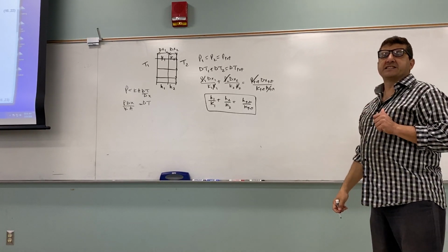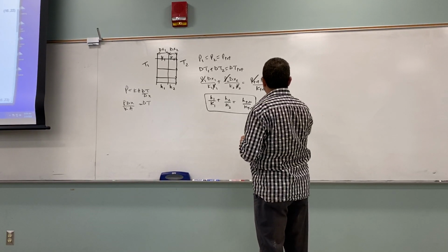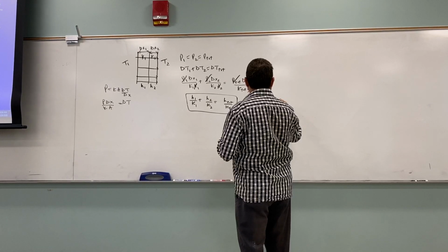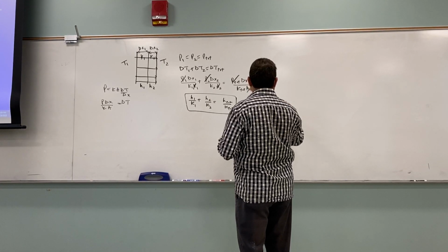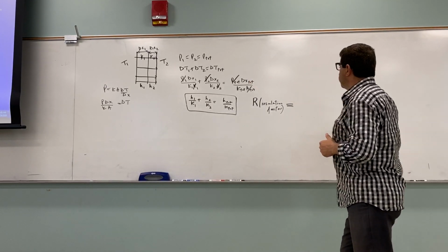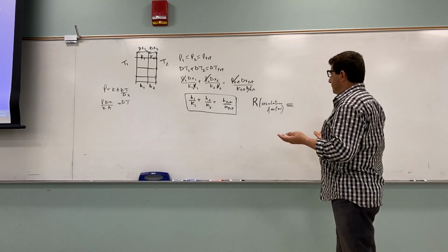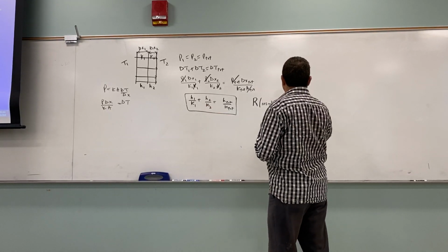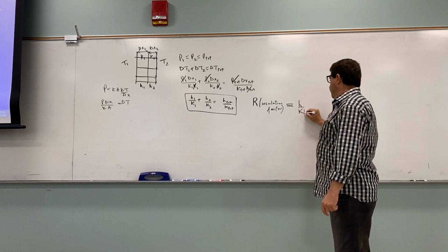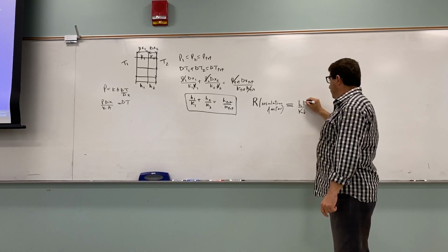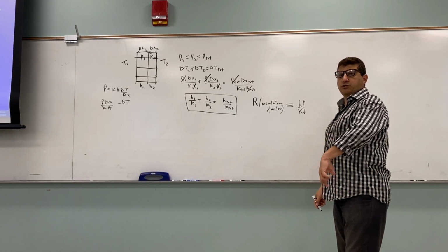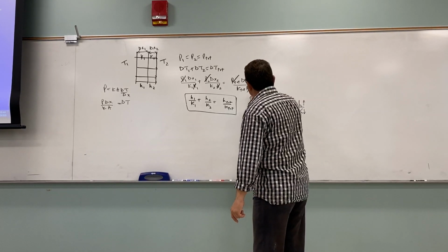Now we're also going to define something else. This is just a definition called insulation factor. The definition of that, when I do 3 lines like this, it means that's basically how it's defined. So the definition of that is going to be H over K. So in other words, something that has low conductivity and it's also thick is going to be the best insulator. If the conductivity is low and it's also thick, the insulation factor is going to be the best.